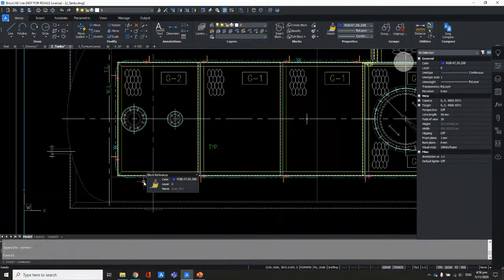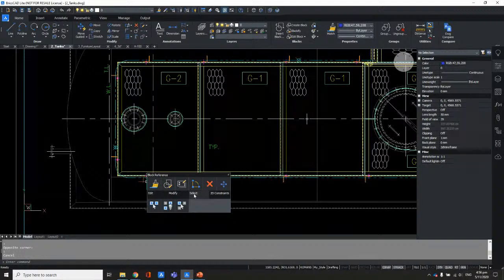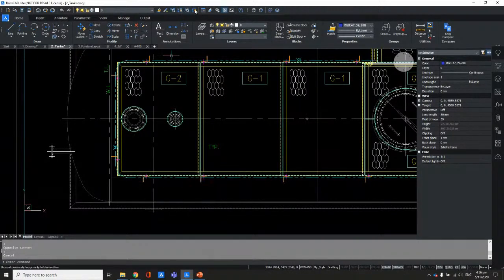And if you wanted to know where else this is in your drawing, you have an option here inside your quad, or if you're not comfortable with the quad, you can also put that functionality here as one of the toolbars that you might want to use. Select similar.